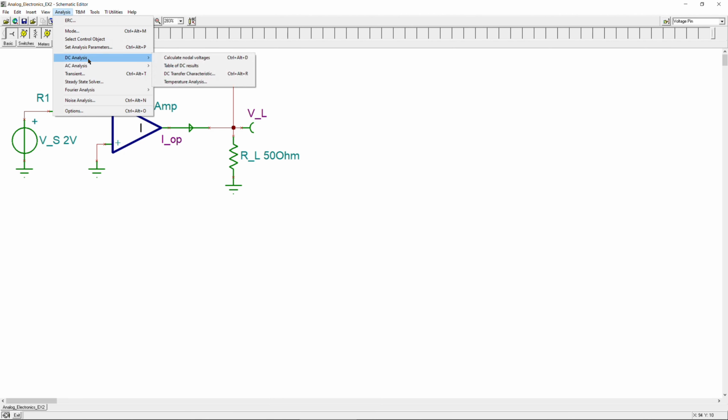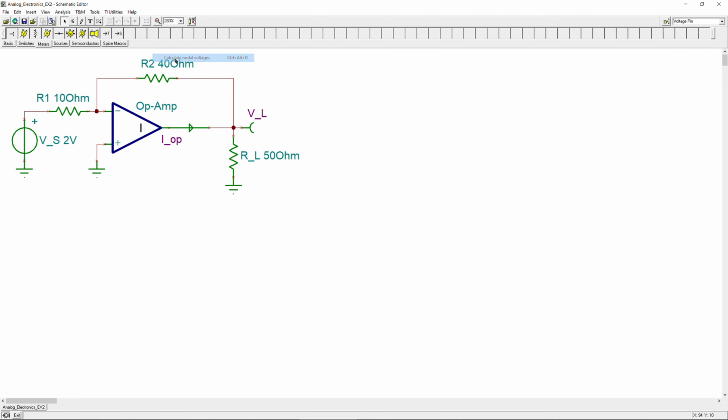Now let's do that. Analysis, DC analysis, and going to the node voltages. And that means everything which you have put in here as a meter, which you see is exactly -360 milliamps as calculated, and also the -8. You can also click on this. You can directly see its voltage and also its associated current. So it will be highlighted in red.